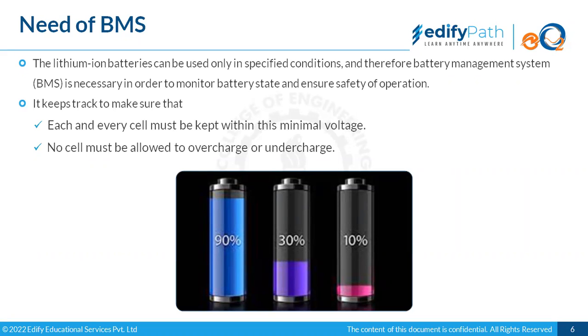Typically, even a small battery of say 2 or 3 kilowatt hour with a nominal voltage of say 72 volt would contain around 300-400 cylindrical cells. Maybe we are bringing all the cells from a similar manufacturer, made in a single lot, and we would be fully sure when we are assembling the battery pack. But conditionally, every cell would be performing in a different way.